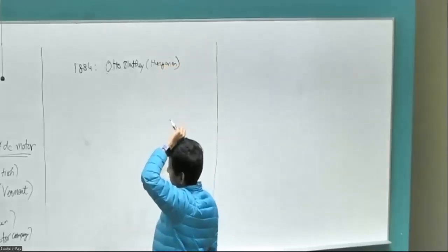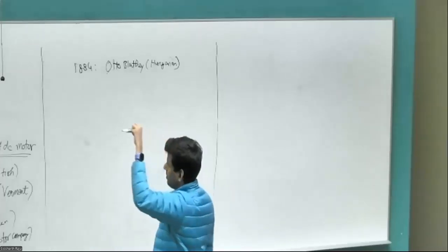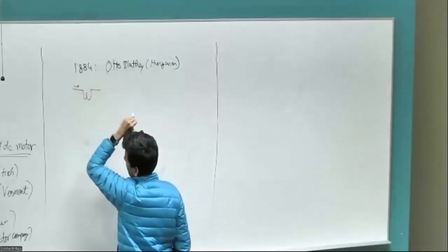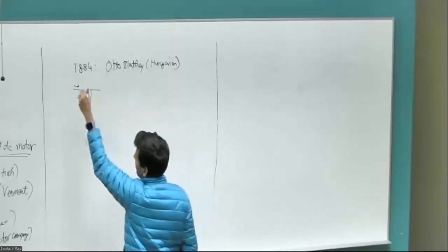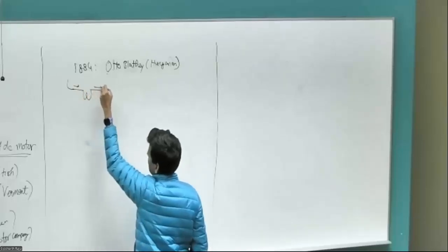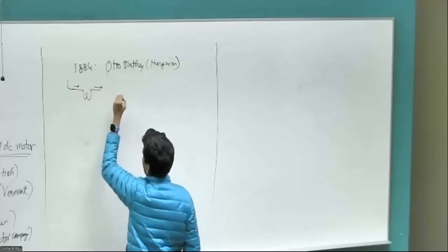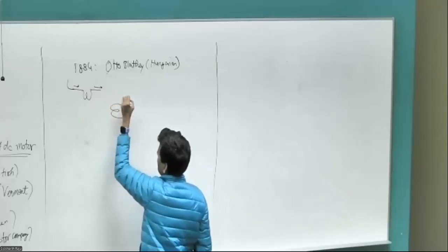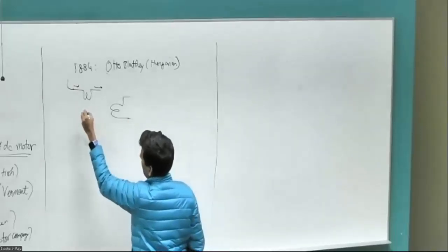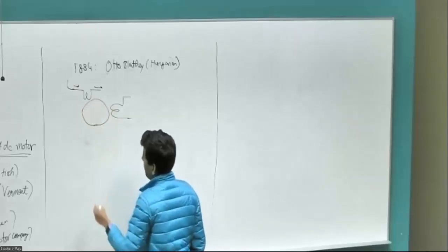He creates what is essentially a power measurement device. So it's a coil which carries current. Let's say you have an energy meter in your home. Before coming from the utility, there is a current carrying coil, and then the output of it comes to your home, the wire. And in addition, the voltage is also measured. So across this coil, the grid voltage is directly connected, whatever is coming from your utility. And between these two coils, these are maintained at 90-degree separation physically.